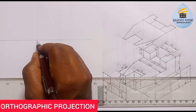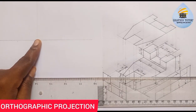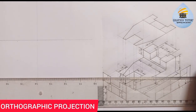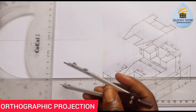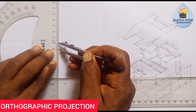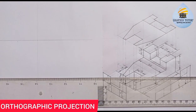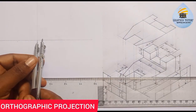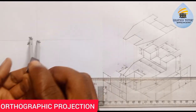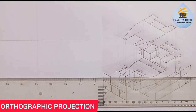Now this is where they are meeting. So from this point, measure 10 millimeter each in all direction. What did I mean is this. Take your compass, place it on your meter rule and measure 10 this way. Can you see that? And you come here, you mark 10, you mark 10, and also mark 10. This is what we have here.